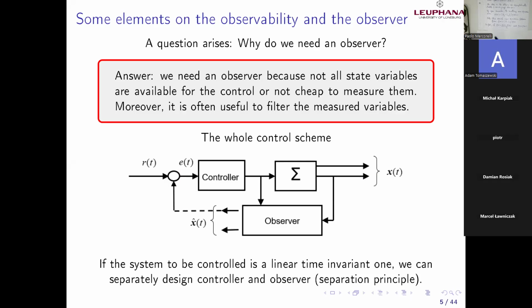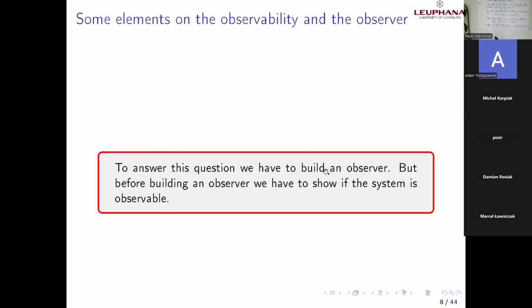The case of the MPC is clear. I need both current and velocity, but assuming that I have just the current, I can measure just the current. How can I proceed? I would like to also have information about the omega. Here it is not an MPC, because an MPC needs both. It's not a control. But the idea is to measure just one of both and to estimate both, what I measure and what I don't measure. Very important, what I don't measure, of course.